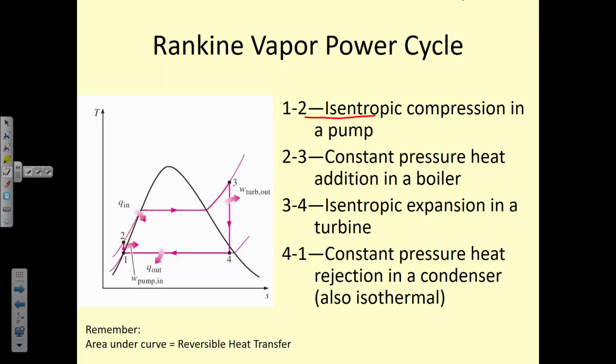Yeah, and a vapor that's very superheated is often called a dry vapor for that very reason, that there's less liquid that's about to condense in it. So even though it maybe contains the same quantity of water, it's in the vapor form rather than the liquid form. So then when it comes out at state 4, is it just like normal steam? Yeah, it's what we would think of as steam, like steam coming off of a boiling pot usually.